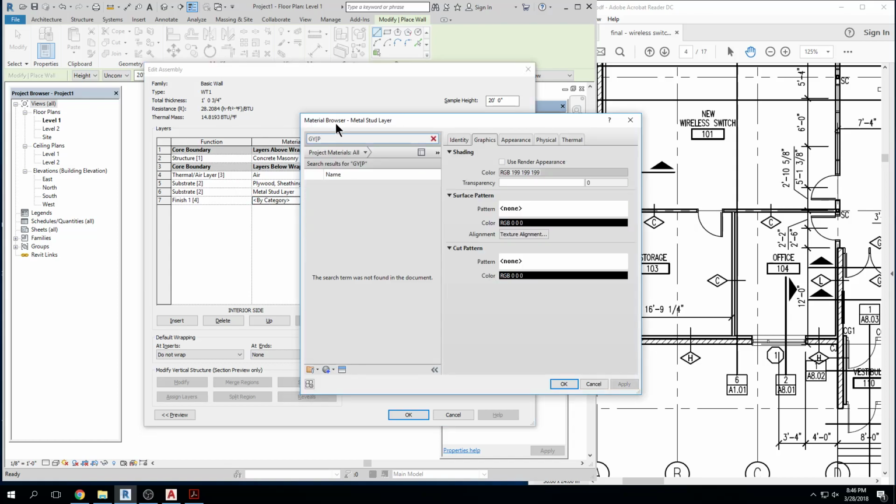So on the wall type they have in the plans, there's the CMU, the inch gap, and then the metal stud. And overlapping the inch gap and half the metal stud, there's like a blow-in. Oh yeah, like the spraying insulation. Is there a way of putting that? Revit won't allow you to overlap them. So that's something that you would just draw in like a detail. Yes. Okay. Yep, exactly.